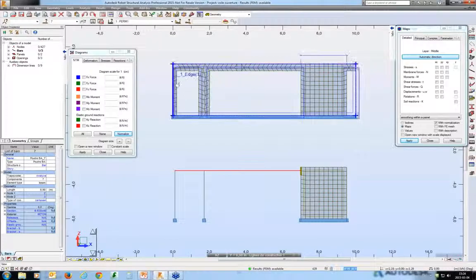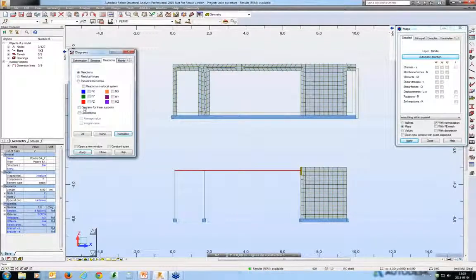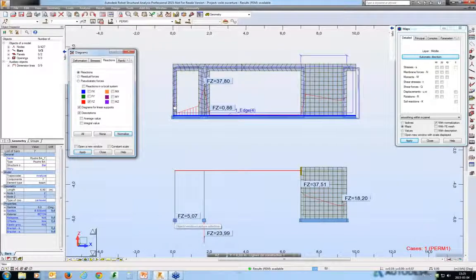Finally, if you look at the way the top model is defined, it is a larger panel with openings, and we have the linear support defined at the bottom of the entire length of the top panel. If you look at the values of vertical reactions, here you have a nice diagram below the wall, and you have two values of vertical reactions under the column, and this is what you need. Whereas here, this definition of the support along the openings just makes the diagram useless. So, let me go back to PowerPoint.